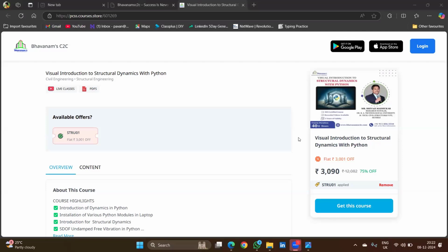If a magnitude 6.5 earthquake comes, the structure will have a certain amount of damage for which I need to pay, and that is repairable damage. The building is not going to go beyond repair, so you can easily repair and reuse it. If a magnitude 7 earthquake comes, my building is going to go beyond repairs and is near demolition stage. That much information we can give by doing a complicated nonlinear structural analysis, and we can say what our building's performance is.